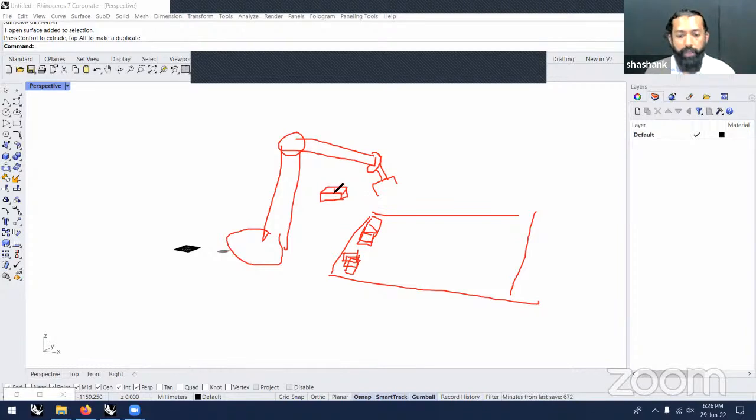Or maybe you can try to create a wall. A few things must be kept in mind. To start, you need to identify this position, the center and the top of the brick onto which the robot is positioned. Move it up, clear it to a point X in space. From there, it goes vertically to a point Y, which is going to be above the location where it's going to rest. And finally, it is going to be positioned on the work object plane.